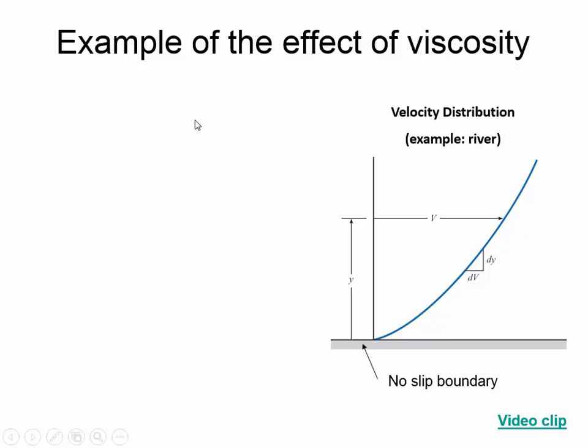So this is an example of fluid viscosity. If it's water that's flowing through a stream, we'd have one profile. But different substances would give us a different velocity profile because of the viscosity. If it was pancake syrup that's flowing down a river, it would be moving slower. And so the velocity profile would be shifted to the left, because for a certain shear stress that we're applying, which is the slope of the river, it would have less of a deformation. It would be a lower velocity.